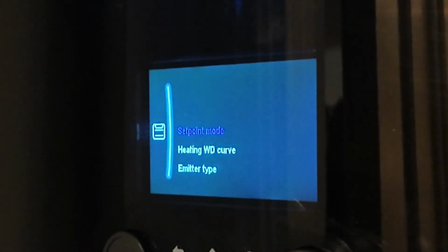But that leaving water schedule, as you previously entered it, is still in operation. So you can still have setback temperatures even though the heat pump is under thermostatic control. I thought it was a bug to begin with, but to be quite frank, it's a very useful feature to have.